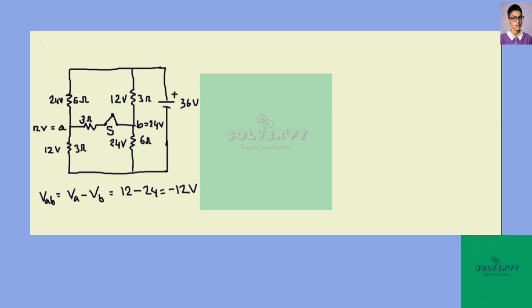Okay, now the switch is closed, right? So when the switch is closed, we can give some currents. Let us suppose that current I comes from the battery, and suppose I1 goes along this way. Whatever we did so far does not have anything to do with this now. The voltages that we have written are of no use now, because that was when the switch was open. Since the switch is closed, we can just neglect those. Now current I gets divided into two, I1 and I minus I1.